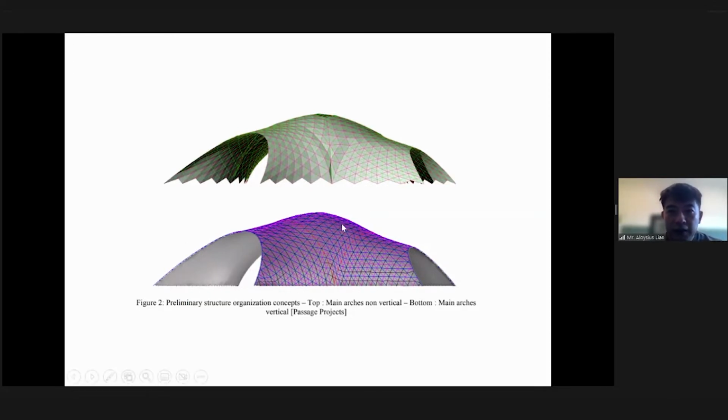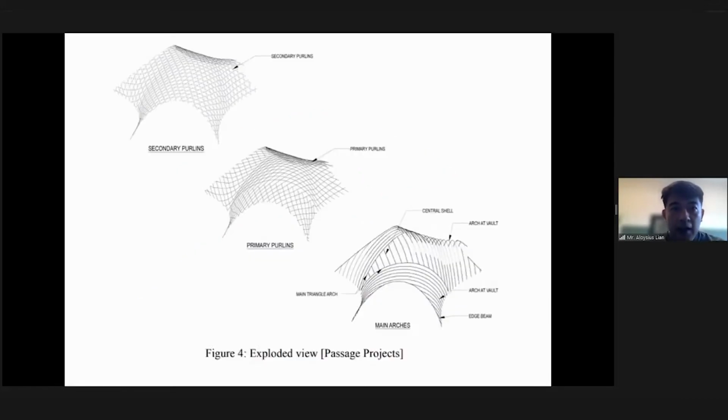If you were to do this in a simple modeling program that you are familiar with, like SketchUp or Revit, it would have taken up maybe hundreds of megabytes, maybe even 1 gig. But this Grasshopper file is only a few megabytes because essentially it just carries the information for the orientations of the panels and where the structural lines will lead towards the forces below.